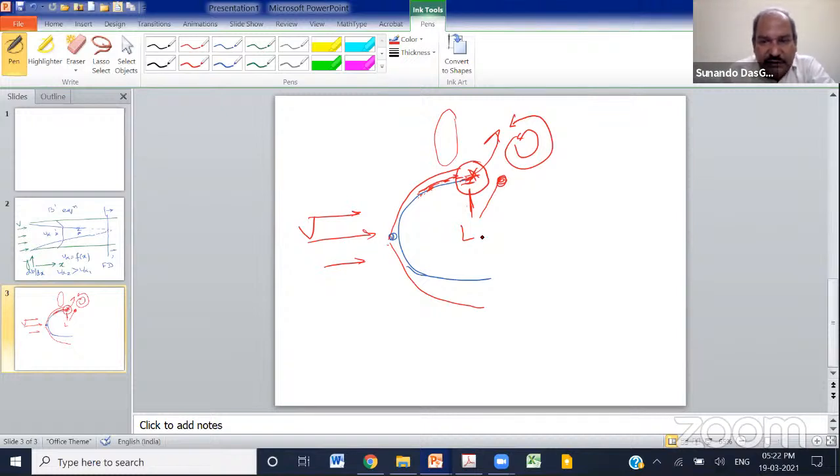That is your question. To answer it, when the particles are moving in turbulent flow, they carry with them more momentum as compared to laminar flow. So to bring a fluid particle which is moving with a higher velocity, and therefore more momentum, to rest, you need to have adverse pressure gradients acting on it for a longer time.